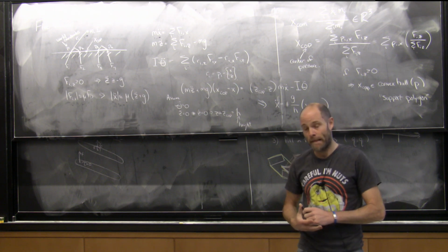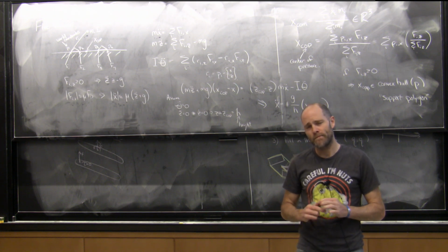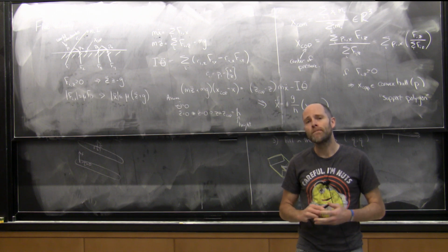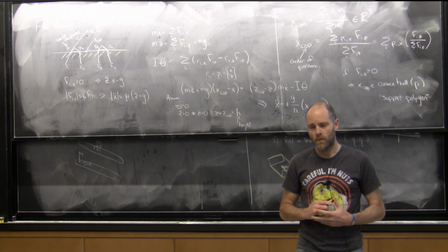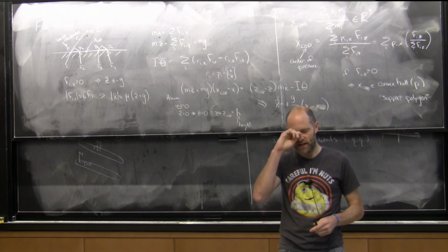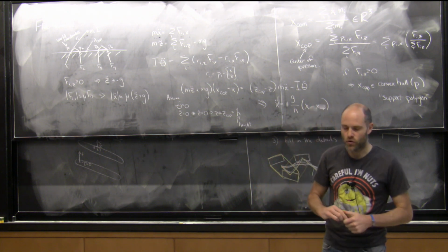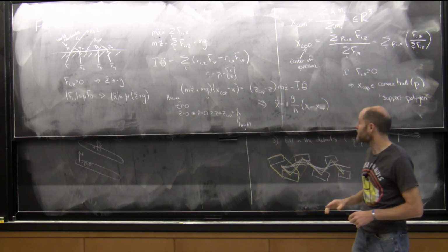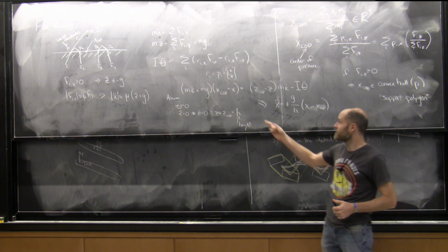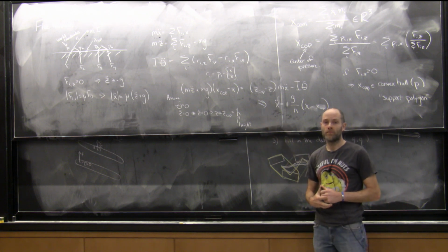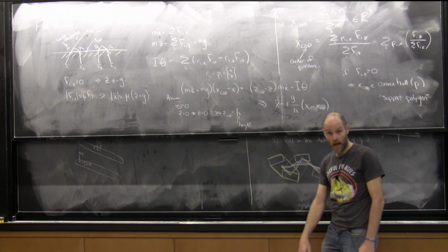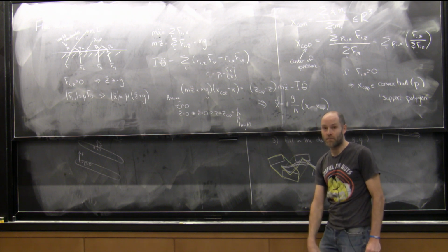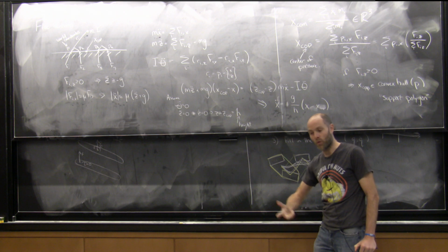Yes. So in the model, we assume that we're controlling the forces at the feet, but on the actual robot, you're controlling the torques of the joints, right? So is there an easy conversion from the forces that you found? It's a really good question, and it's not actually that we're controlling the forces at the feet. The recipe here is that this prescribes ultimately a center of mass trajectory. So if I have the kinematics of my feet and I've stayed inside the friction cone, which I'm going to do if my center of pressure is inside, I certainly won't tip off.